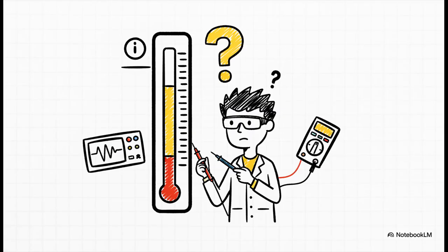And yeah, let's not forget that negative power supply. When you're working with ECL, your ground reference at 0 volts is actually the most positive point in the whole circuit. If you're used to TTL, that is completely backwards, and trust me, it can make probing and troubleshooting incredibly confusing until you really get your head wrapped around it.